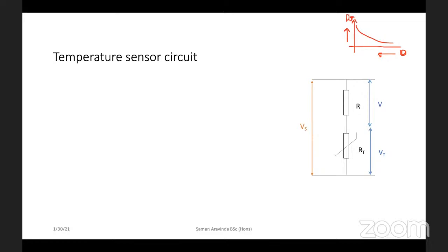I hope you remember how the temperature and resistance are related in a semiconductor. Remember, if the temperature is increasing, the charge density increases, it increases the current. If the potential difference is constant, that reduces the resistance. Or in other way, if you use the band theory, if you increase the temperature, energy from the radiation by heat is absorbed by a lot of valence electrons, and a lot of valence electrons go to the conduction band, so that the current increases, so that resistance also reduces.